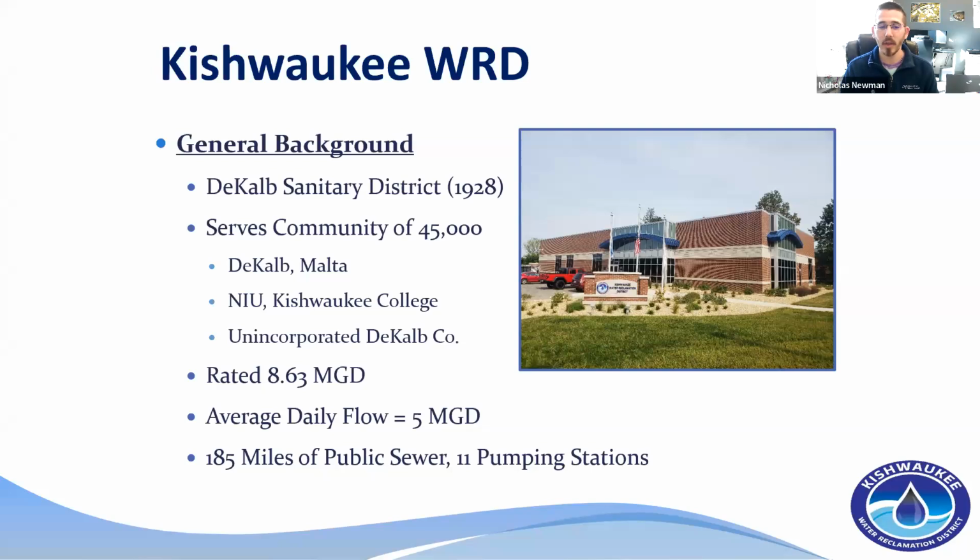Our facility certainly falls into that small to medium size range that Dr. Moore was referencing. We're rated at 8.63 MGD. Our average daily flow is around 5. And with this expansion that we've recently done to these other areas, we are now sitting at about 185 miles of public sewer in our collection system with 11 pumping stations that involve force mains.